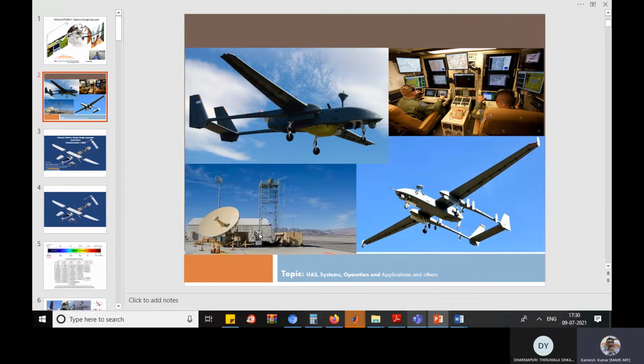If you are going with a 200 or 300 kilometer flight range, then you can go with RF communications using a very large antenna, around 12, 15 or 20 feet in disk area. This can support communications around 300 or 400 kilometers. But when you are flying for 1000 kilometers, you should have different communications, because this cannot work beyond line of sight.